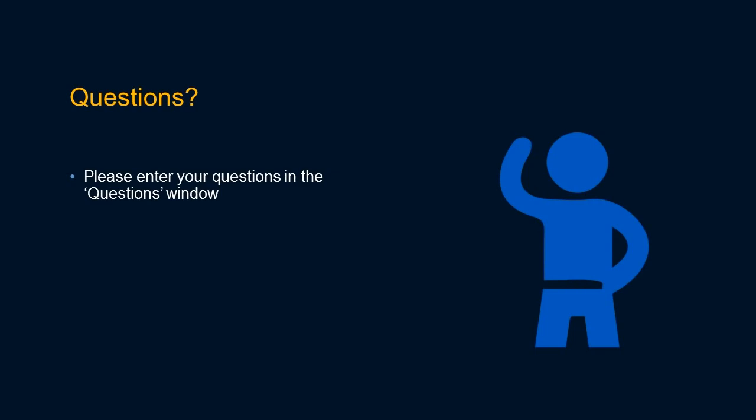BACnet is essentially a different protocol. So you've got Modbus, which defines for you how those ones and zeros in the data packets are interpreted. Which of those bits are the address I'm trying to talk to? Which of those bits are my commands? And I'll talk a little bit more about how Modbus works in a moment in that regard. But BACnet's essentially a different protocol, so it's going to have its own descriptions of how it's going to function and how I'm going to react to that. Without going too much into that, essentially what you need to know is that BACnet's just another version of a serial communication protocol.